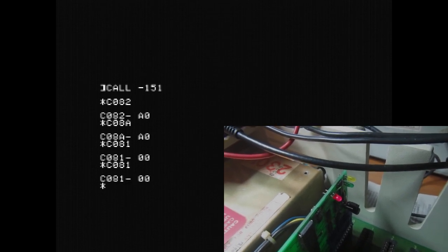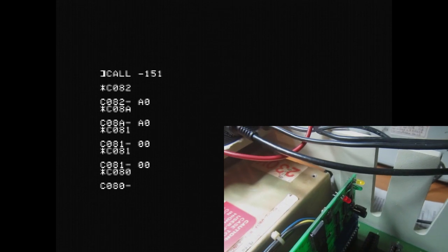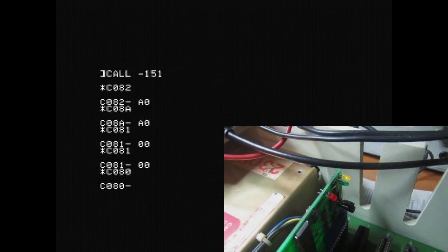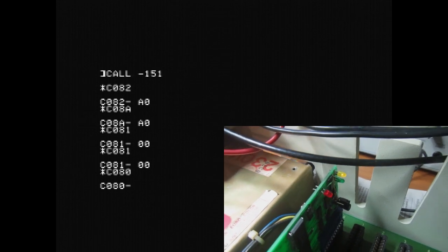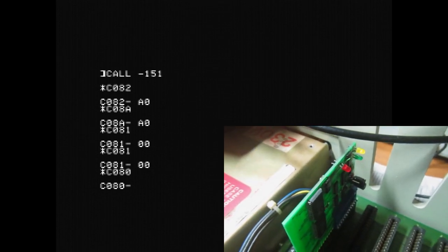But if I enable the RAM in read mode at this time, since there is nothing on the RAM, it just started the machine with random contents. So if I enable the RAM read, the red LED will go off, and the yellow LED will light at this time. Yes, it does, but the machine solidly crashes. It doesn't respond to anything, because of course the monitor and the BASIC are running from ROMs. So I just disabled all those onboard ROMs, and the machine crashed. It cannot execute any meaningful thing from the RAM at the moment.